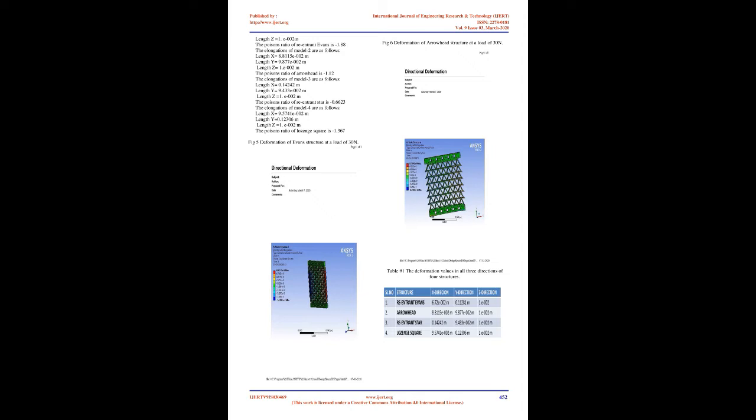They expand and shrink like this due to an interconnected network. This unique property offers enhanced functionality in the properties of structures. Compared to conventional structures, negative Poisson's ratio, NPR, structures offer increased plane strain, tunable density, fracture resistance, shear modulus, and acoustic response. The NPR structures have been considered for a wide range of smart and functional devices, including smart antennas, stretchable sensors, protective equipment, and in many other applications from the fields of nanotechnology and biomedicine to defense and aerospace.